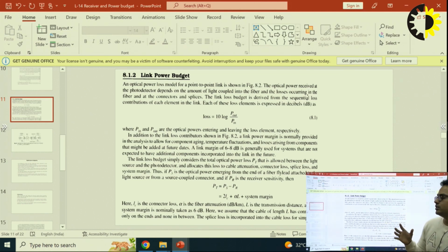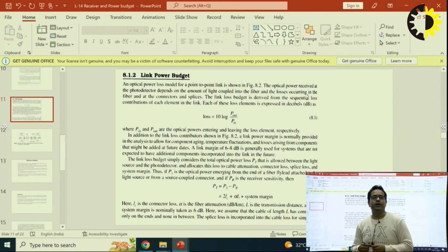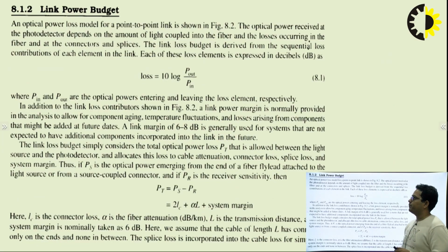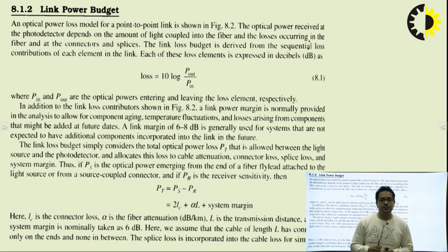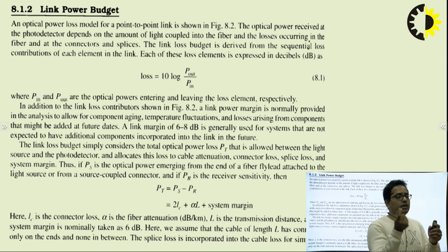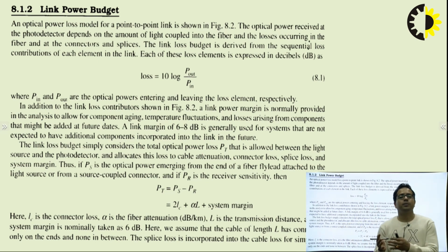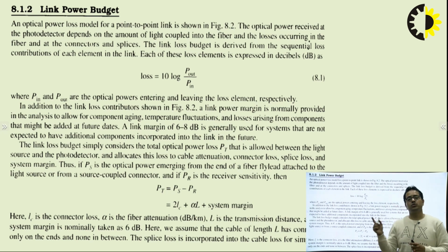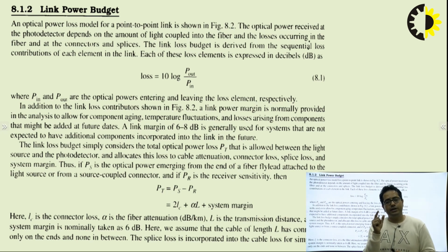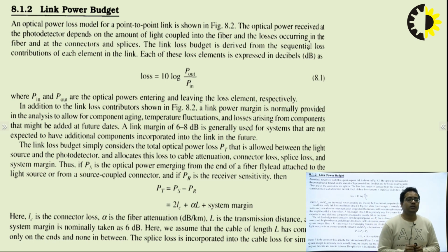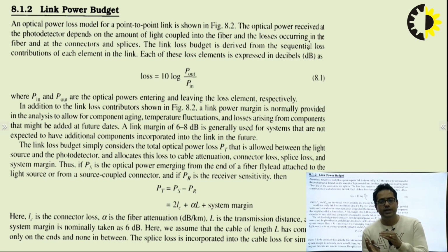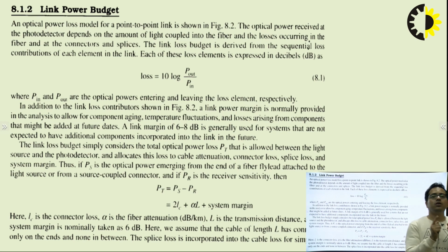So this laser, which has a spectral width of around 1 nanometer, is a very attractive point related to the way in which we can couple the optical signal into the optical fiber, because we have seen that the very first important requirement for a good source is a very narrow spectral width. This narrow spectral width can be efficiently coupled into the fiber, especially the single mode fiber, which can be used for long distance, high speed communications.